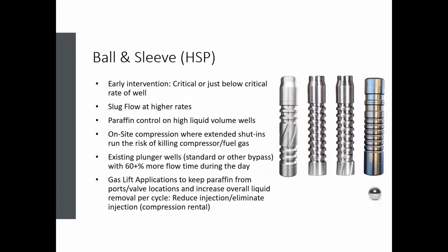Ball and sleeve selection is dependent on the gas and fluid rate in the well. In general, high rate wells have longer sleeves and heavier balls, and the opposite for lower producing wells.